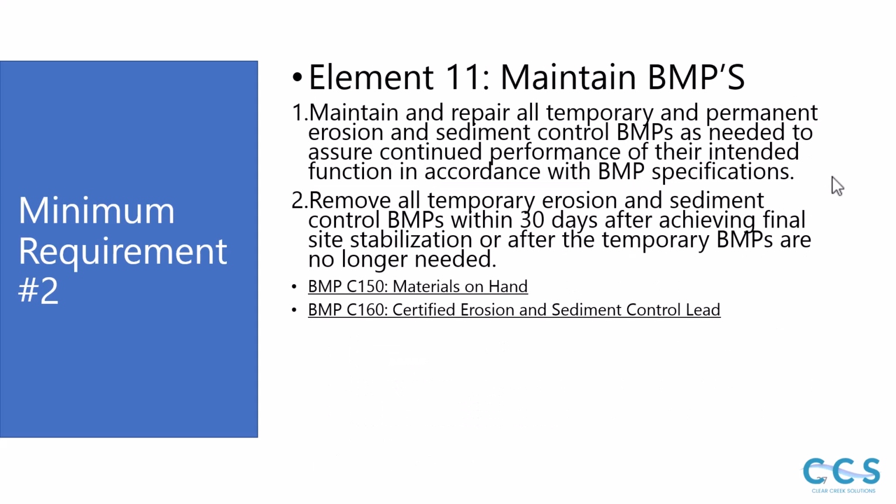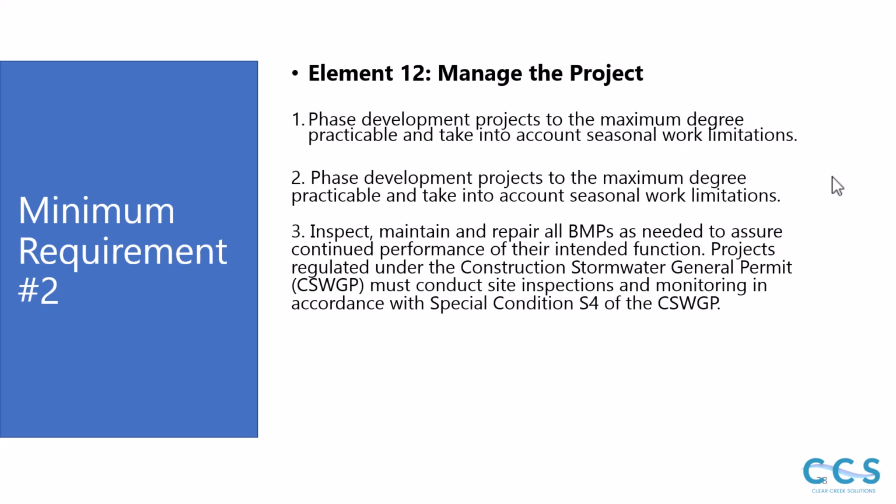And now on to element 11, which is maintain the BMPs for repair and remove all temporary erosion and sediment control BMPs within 30 days. Materials on hand and certified erosion and sediment control lead are the 2 BMPs there. And for element 12, we need to manage the project, phase development projects to the maximum degree practicable, and take into account seasonal work limitations. Inspect, maintain, and repair all BMPs as needed to assure continued performance of their intended functions.